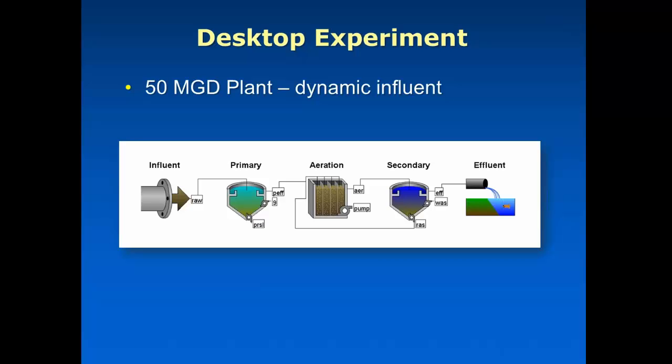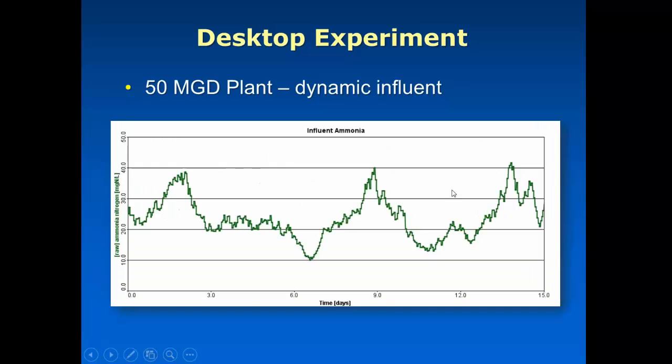So the influent comes in. There's some primary clarifiers there. There's a conventional plug flow activated sludge tank, and this is using diffused air. And then we have a secondary clarifier with the recycle, and then all of the concentrations of ammonia that we want to control are coming out here at the back end in the effluent. So pretty standard type of model that we would use.